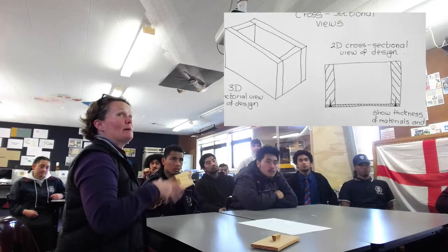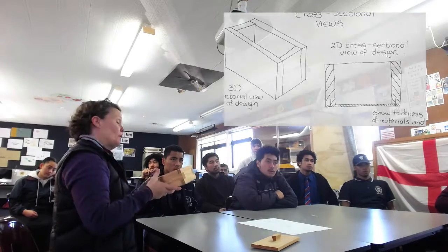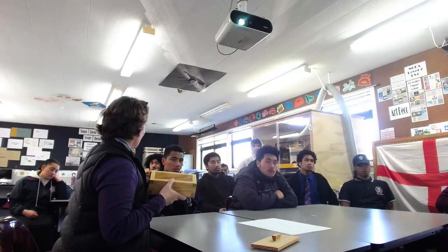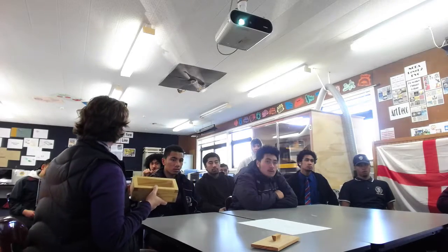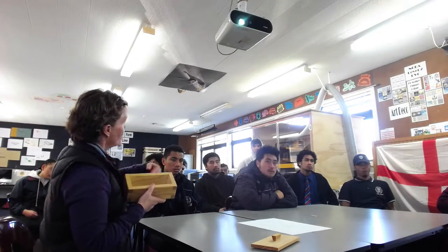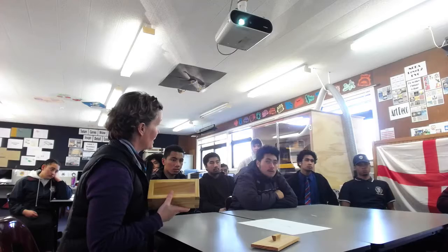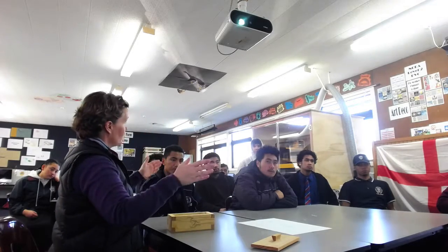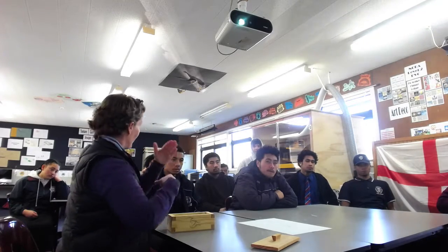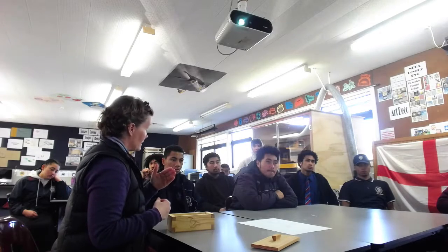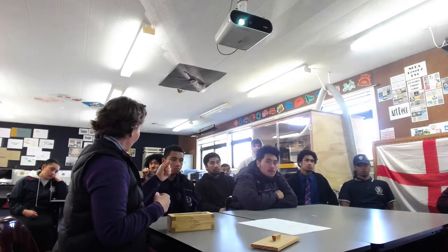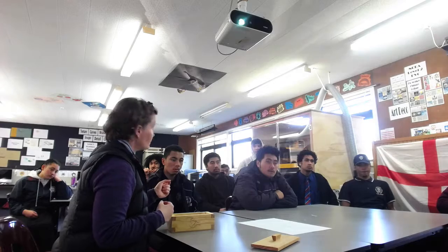So any surface that's been cut, see the notes down the side, you put 45-degree lines across. Anybody looking at your cross-sectional drawing knows that that's a cut edge, because that means cut edge. If you had a drawing board out, those would have to be done with a 45-degree set square. When we're sketching, we just kind of guess 45 degrees.